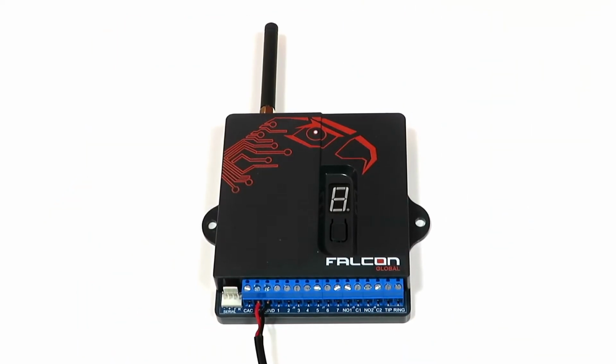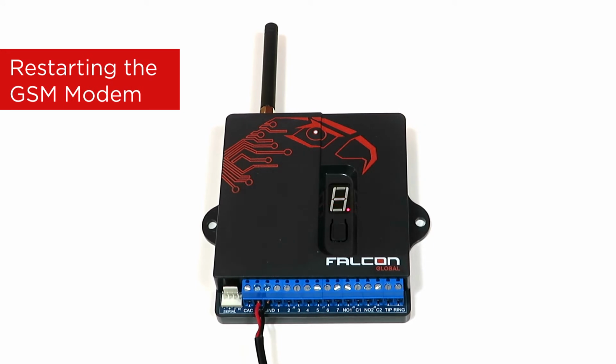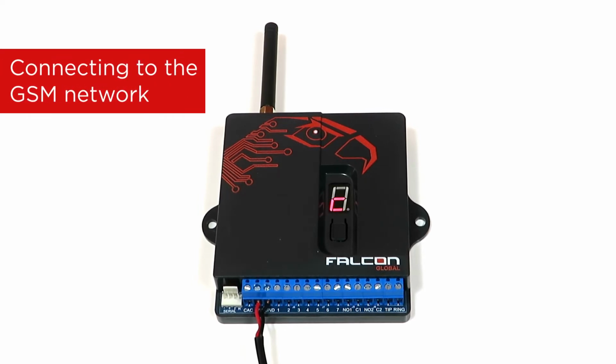When you apply power to the Falcon, the first thing the 7-segment display will show is the firmware version. In this demo, it is 428B, which is version 4.28, and the B indicates the hardware version. It then starts the initialization process, just like when you would switch on your cell phone or PC. The R means that it is restarting and powering up the GSM modem. The I means it's initializing, that is, it's getting the modem ready to connect to the GSM network. And the lowercase c means it's in the process of connecting to the GSM network.